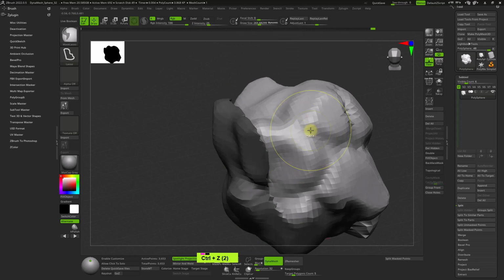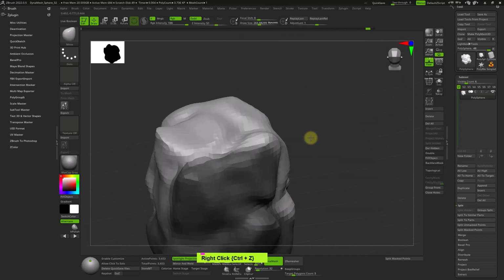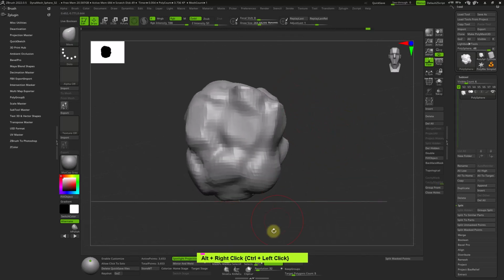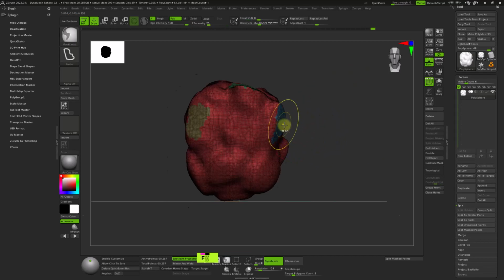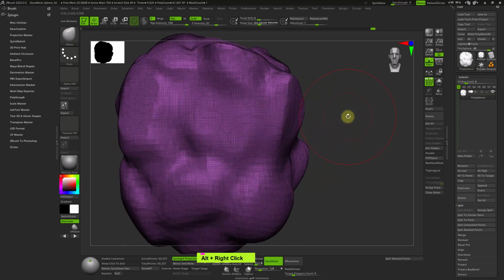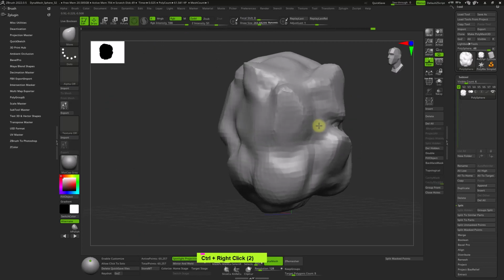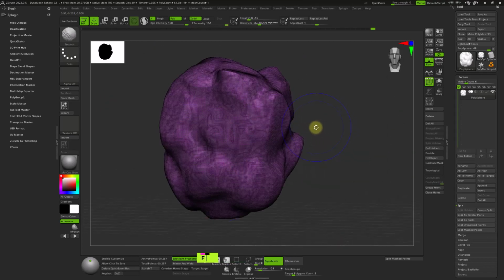Now here, let me undo this, and the reason I'm doing this is because the resolution looks to be small. So I will update this to about 128. So, and Tab and Ctrl drag, and this is how it looks. And Ctrl V, we don't want any crazy subdivision.